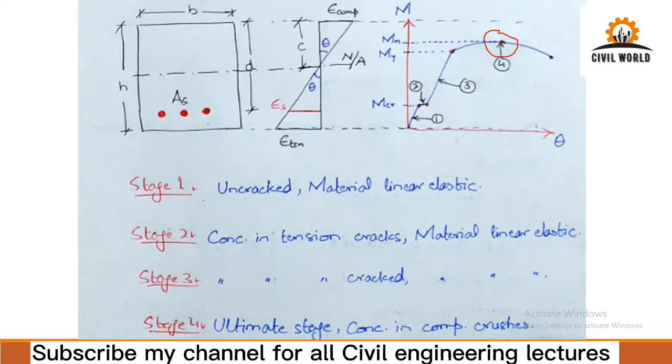So in stage one, we have an uncracked section and materials are linear elastic. Stage two, concrete in tension cracks. Materials are still behaving in a linear elastic way. In stage three, concrete in tension has already cracked. In stage two, materials are still linear elastic. And in stage four, that is the ultimate stage, materials are behaving in a non-linear, non-elastic way, as you can see over here. And concrete in compression crushes and the beam fails.